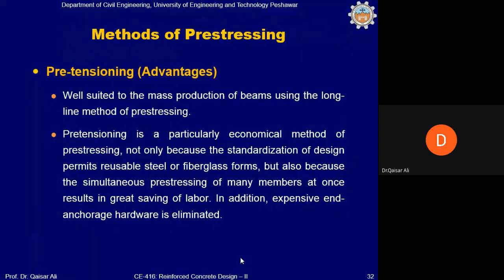नीचे नहीं रखेंगे, मैंने कहा कि जो स्ट्रेच हम करेंगे, तो स्ट्रेच करने के बाद हम वायर्स को उसी स्ट्रेच पोजीशन में छोड़ेंगे, तो जैक भी उधर होगा, क्योंकि जैक के जरिए आप उसको स्ट्रेच करेंगे। तो जब स्टील वायर काफ़ी अरसे तक स्ट्रेच पोजीशन में हो और आप इसको साइट में इस्तेमाल करेंगे, तो चांसेस हैं कि कोई आके इसको छेड़ दे और नुकसान हो जाए, क्योंकि वो बहुत ज़्यादा हाई टेंशन में होता है, अगर वो काट देंगे तो ये बुलेट की तरह शूट करता है। इसलिए साइट के लिए मौजूद नहीं है।